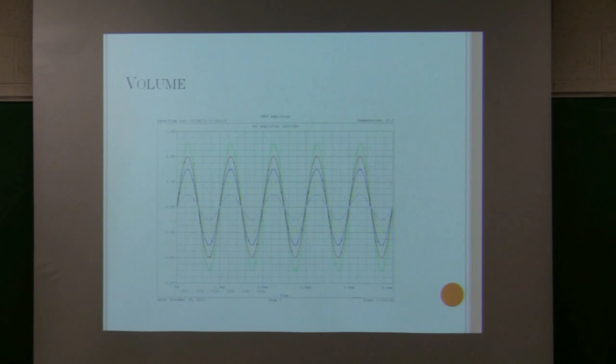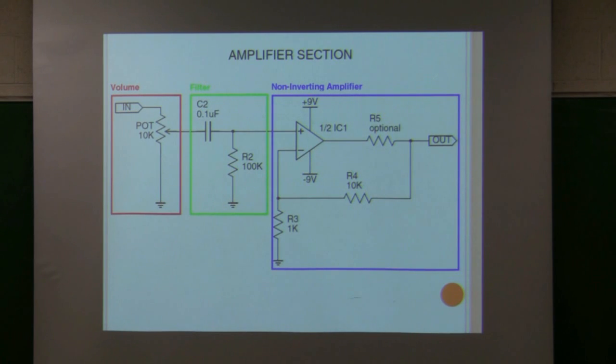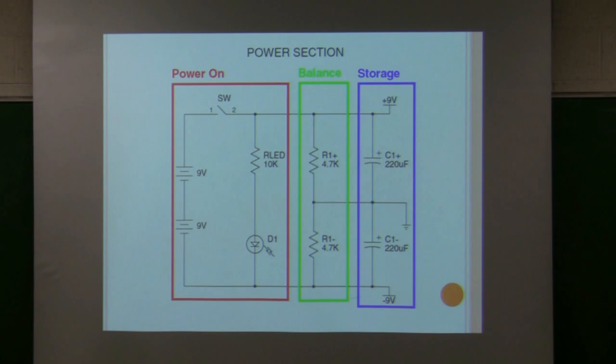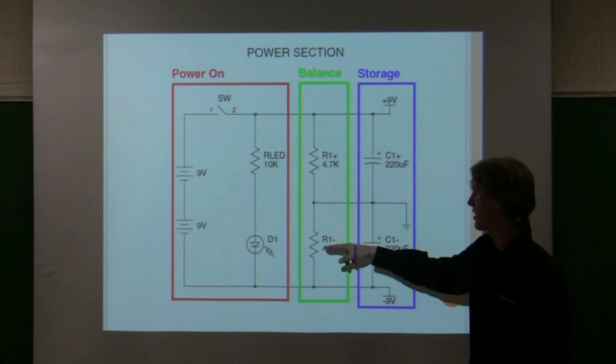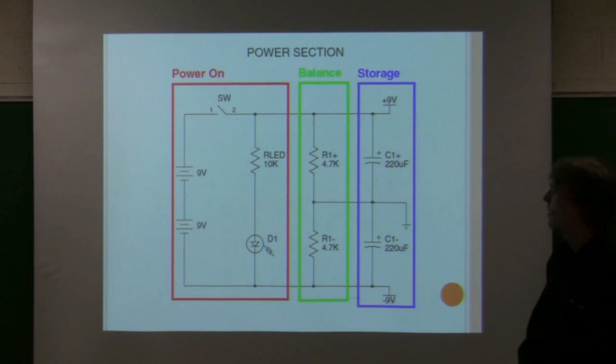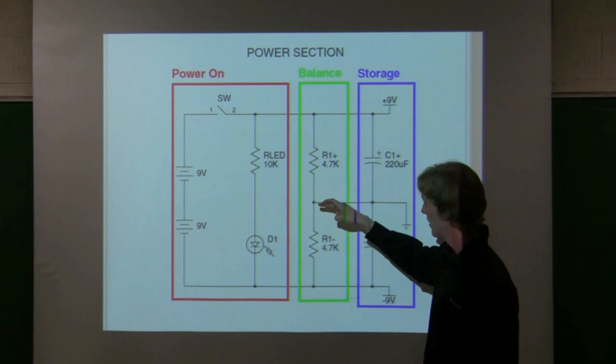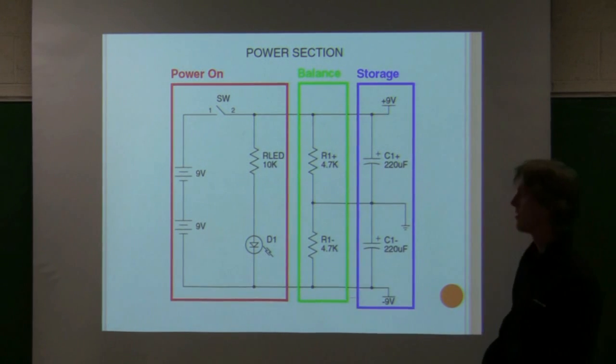So the second, the one in the green, the amplifier circuit, I can go back to it real quick. It runs off two power supply voltages, plus 9 volts and minus 9 volts. A battery only gives you one voltage, so what do you do? Kind of the solution is you take a voltage divider, an equal voltage divider, and what you get is, in this case, 18 volts here, 9 there, and then 0 there.